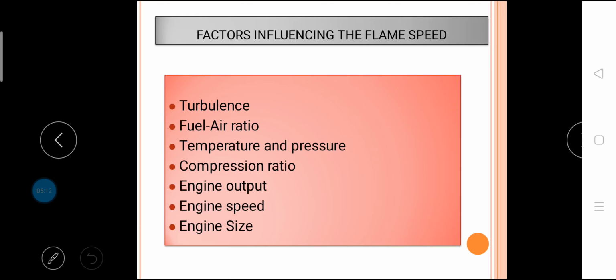Engine speed. The flame speed increases almost linearly with engine speed, since the increase in engine speed increases the turbulence inside the cylinder. The time required for the flame to traverse the combustion space would be halved if the engine speed is doubled. Double the engine speed and hence half the original time would give the same number of crank degrees for flame propagation. The crank angle required for the flame propagation during the entire phase of combustion will remain nearly constant at all speeds.